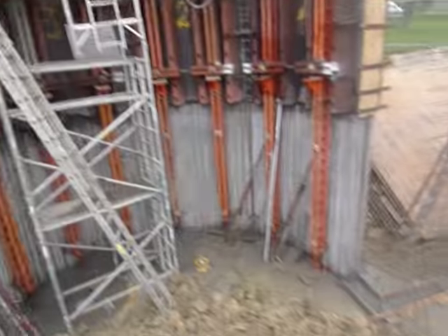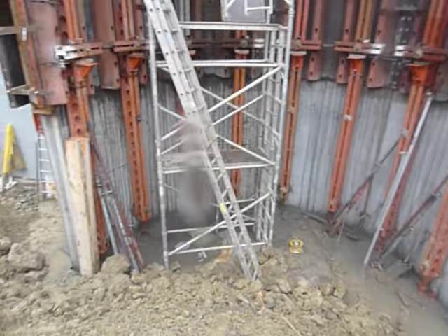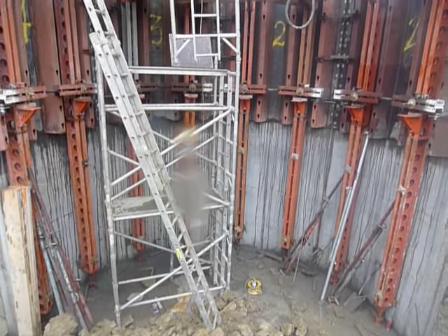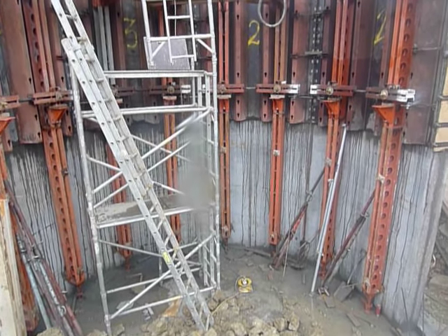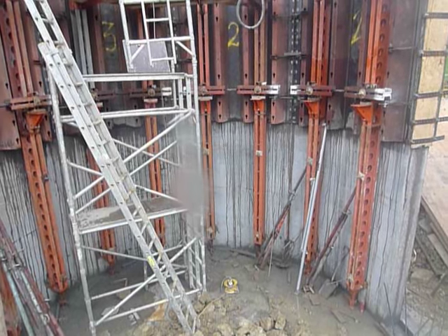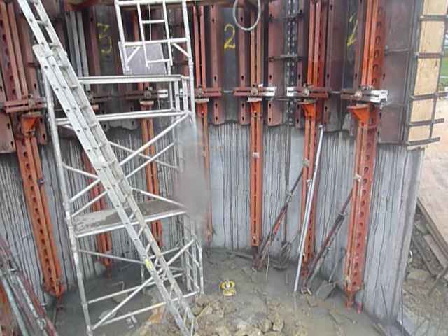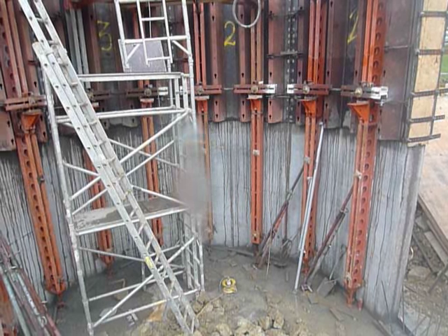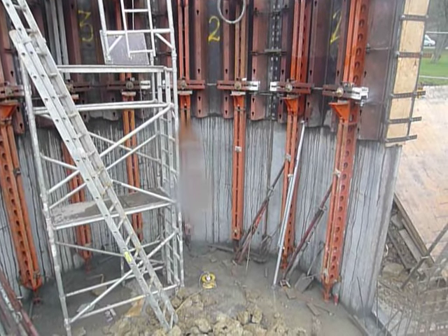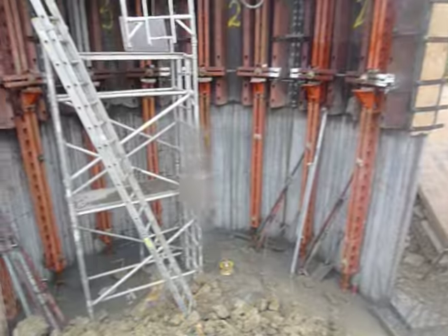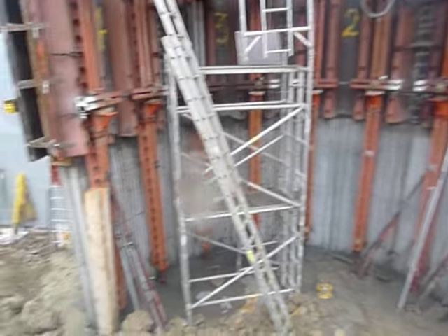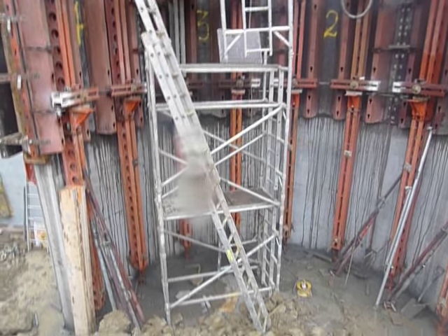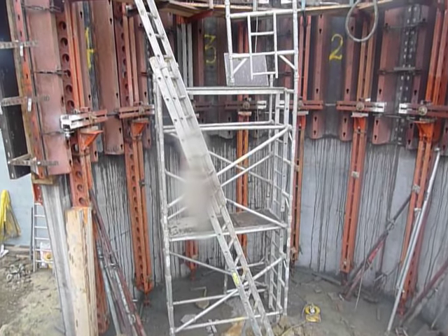There's the shutter in all its glory. Okay, the first pour that we did on our other video showed how the same shuttering system was put on the bottom to a kicker. Well, it didn't even need a kicker if you don't want to. You can actually line it with a steel tape and a series of Hilti nails, and that's what we chose to do. So we had a centre radius point, and I set out a series of nails around the 180 degrees of the curve, and the boys tried to follow that.